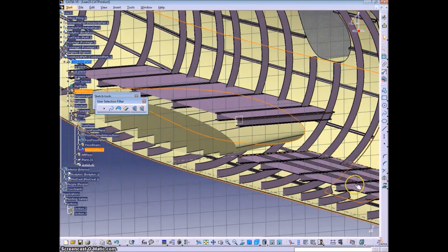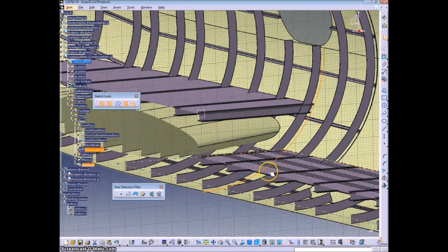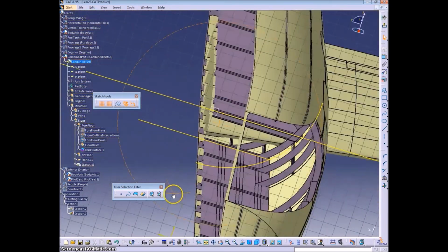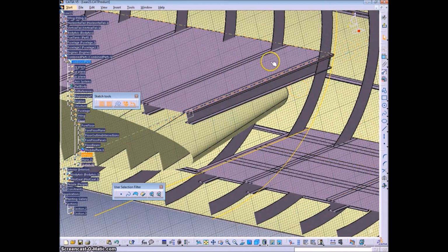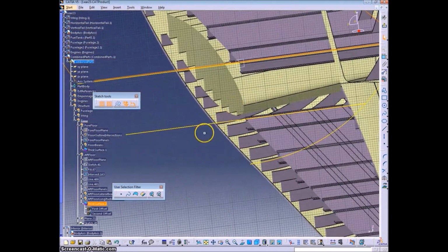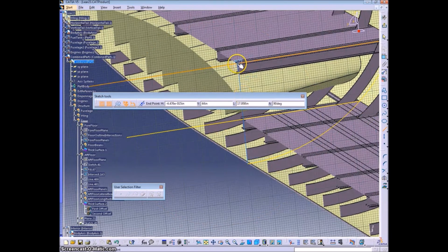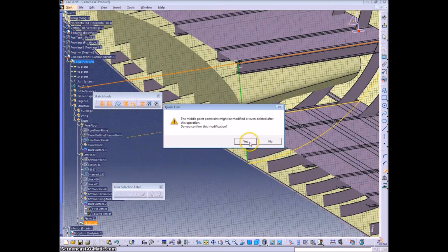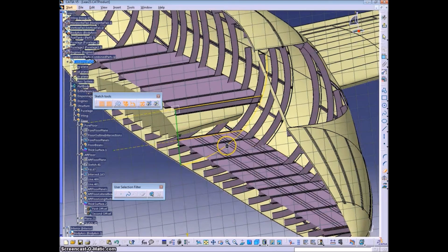And here I'm adding a plane to put in the riser from the first to the second level. We're just going to project the fuselage. Again, it would be a good idea to offset the projection once you get out of the sketch using a parallel curve or just an offset. That way you're not running right up to the fuselage. But once we get this out of the sketch here, I'm only going to do half and then I'll reflect it once we fill everything in that we want.